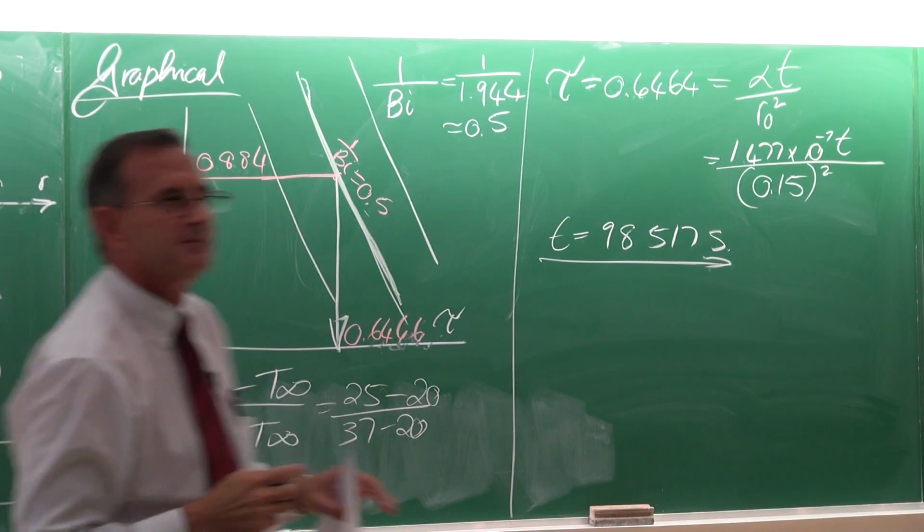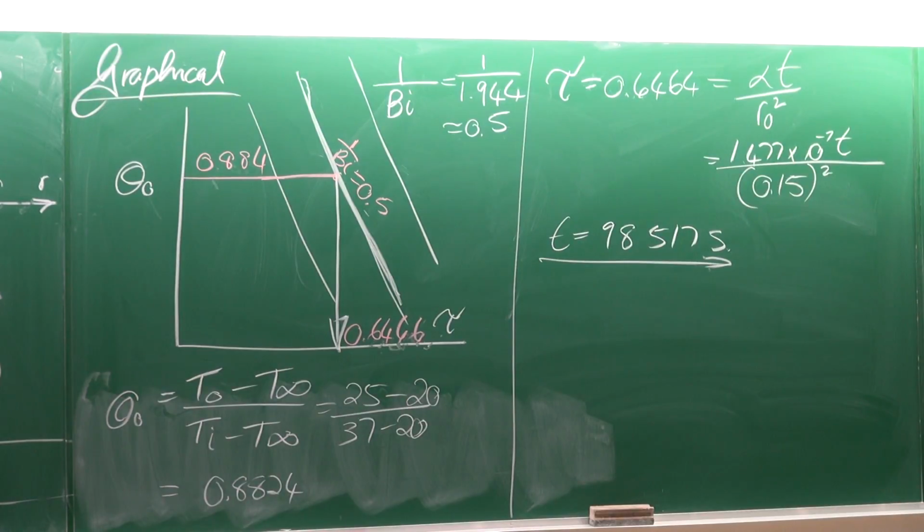Question? I know we calculated that bulk temperature because of the fact that there was the difference. And you said that because we're dealing with something that doesn't change very much, the properties don't change very much over time, so our error percentage is small. What if we were dealing with a substance that its properties change dramatically? Because those properties are changing linearly with temperature, but the temperature isn't changing linearly.